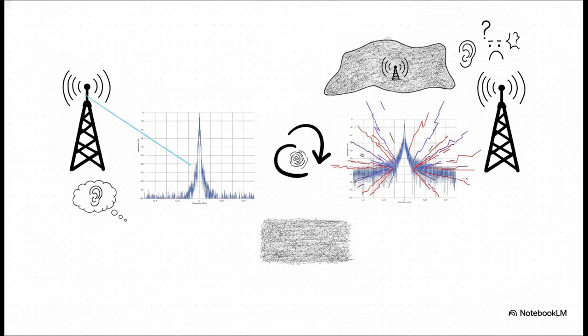Why does this even happen? Well, internal oscillators just aren't perfect. They suffer from microscopic timing jitters that translate into this messy phase noise. When you tune your radio, this local oscillator's composite noise actively mixes with strong incoming signals from nearby frequencies. This dangerous mixing actively raises the receiver's noise floor, essentially burying weak signals in a broad spread of noise sidebands. It's exactly like throwing a thick, heavy blanket of static over that faint station you are desperately trying to hear.